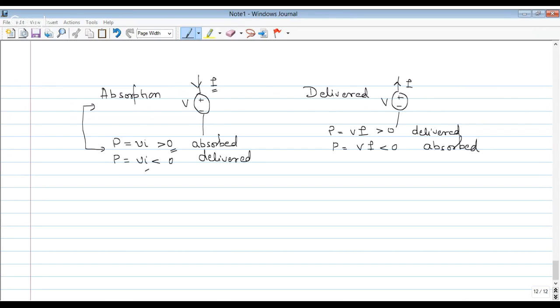How does leakage flux in a transformer depend on load current, and why not voltage, frequency, and power factor? Basically, flux is generated by a current because MMF is equal to N into I and flux is MMF upon reluctance. So the total flux in any machine is dependent upon current.